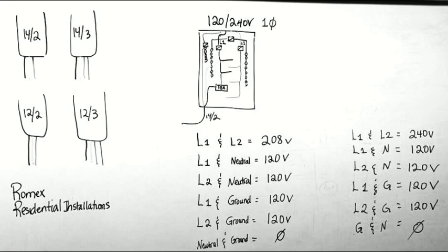You're taking 600 and dividing it by 120, right? 600 divided by 120 gives me how much? Five. Makes sense, 5, right? So if the refrigerator is using 5 amps and the microwave is using 10 amps, when both of them are on at the same time, how many amps are flowing through that circuit?